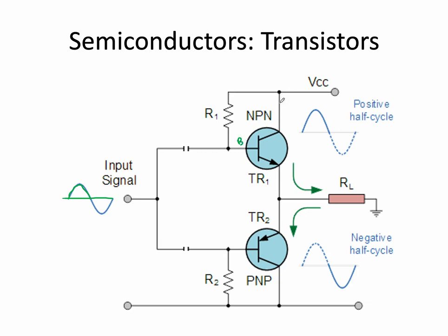And so that'll connect it to positive voltage, which will produce a very large positive voltage here on the output. And then if you change it to, for example, a negative voltage, that will turn off the NPN transistor, but a negative voltage on the PNP will connect this to the ground and produce this very large negative voltage. And so you can create an amplifier.